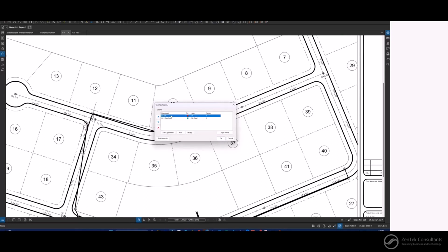So for example, what I've done in the past when I was in the field, I would typically overlay the architectural drawings, and I would overlay some of the MEP, the mechanical, electrical, and plumbing drawings. Sometimes I'd have all 4 of them on the same PDF with different colors. It gets a little bit confusing. 2 of them is what I would recommend most people do.